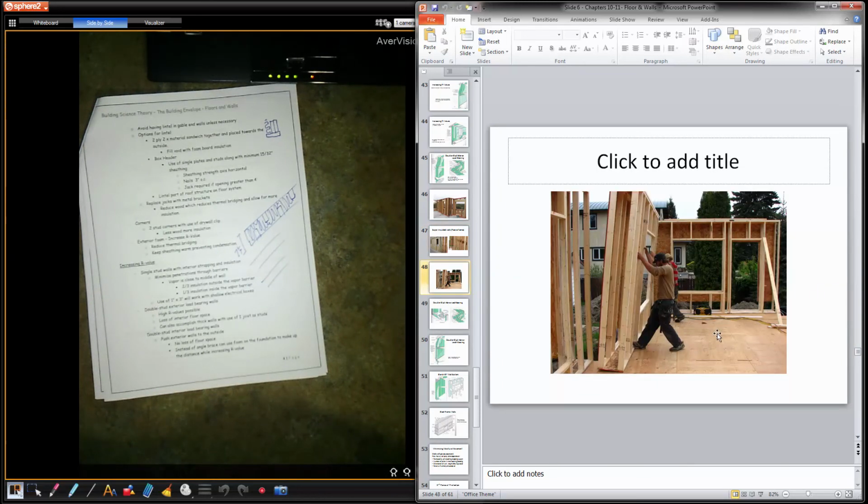Here's another system. So bottom plate is OSB sheathing. 2x4 wall on the inside, 2x4 wall on the outside, and then you get your top plates. See the windows are framed up. No lintels over top, so more than likely the lintels are going to be in the floor system. Massive depth for insulation. Okay. So lots of R value. So you're going to insulate between the studs, you're going to insulate between the two walls, and then again in between the studs.